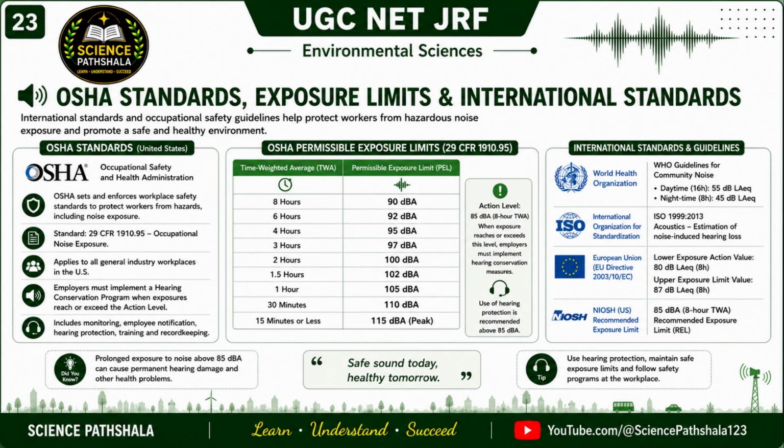Now let us look at the WHO guidelines. As we know, WHO stands for World Health Organization. WHO provides environmental noise recommendations to protect public health and quality of life. For residential areas, WHO recommends that daytime outdoor noise should generally remain around 55 dB LAeq or lower. For nighttime conditions, the recommended level is even lower because excessive nighttime noise affects sleep quality and mental health.